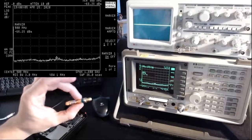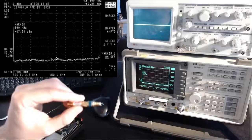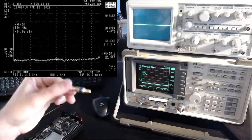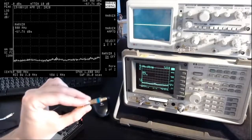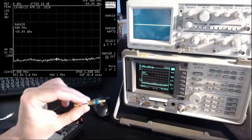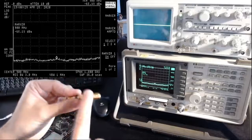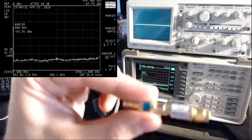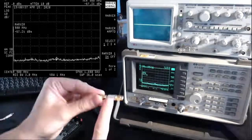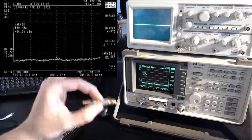So I'm going to inline the cable with these components. One, we already looked at it in episode 4, is a 10 dB attenuator, and we checked that it actually does its job in the 0 to 1.8 gigahertz bandwidth at least. And this is a DC blocker. This little component, which I don't know if it is visible here, is from Mini-Circuits. So this is a decent piece that has a data sheet and some known performance.